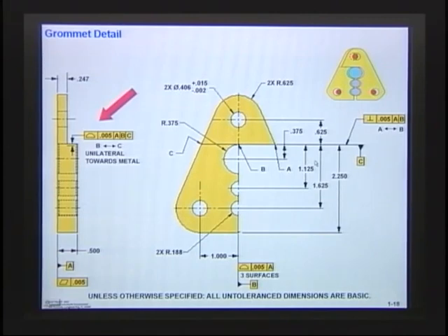So the first thing what I did is I came in, and I'm going to go after the most important things first. So do you notice that this surface, when the 2 parts came together, that surface there, that couldn't be exactly in line with this feature, because if it was exactly in line, we wouldn't be able to get in. So this part has to be on that line, or it has to be down, right?